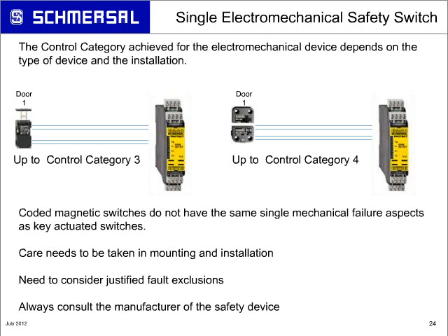And unfortunately, many times what happens is if a key gets bent, somebody may bend the key back into place. That happens a couple times. You start fatiguing the metal of the key, and over time that key could eventually break in the switch. But if you've taken special care in design to minimize that, you can design in what's called fault exclusions, where you're potentially or systematically eliminating a mechanical failure based off of design and installation of the key in itself, for example.